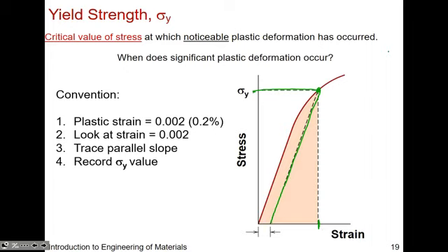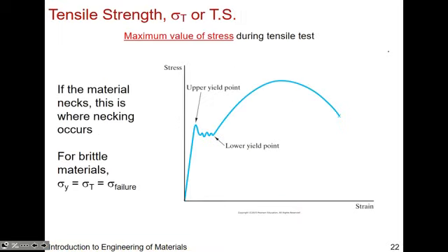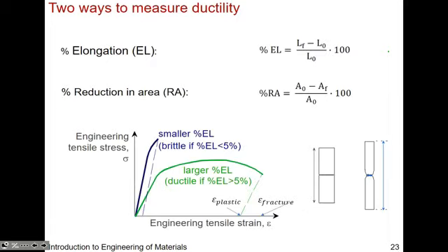The curve for polymers we'll talk about in a little bit. They sort of follow this trend, but the plastic deformation region covers much more strain than, say, a metal. But it would still hold. Okay. All right, so we talked about upper yield point, lower yield point. This is, once again, for a ductile type of material, not really ceramics. We'll talk about necking in a little bit. But before that, we'll talk about ductility.